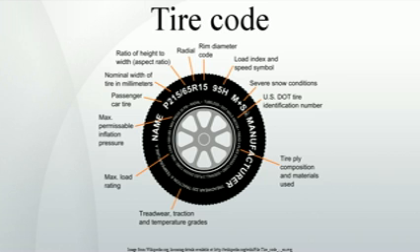MO: original tires for Mercedes-Benz. MOE: Mercedes-Benz Original Extended. N0, N1: original tires for Porsche, where the number is 0 for the first approved in that size, 1 the second. Star: original tires for BMW. RSC in a circle: BMW Run Flat System Component. TPC: General Motors OE fitments. AMX: Aston Martin OE fitments. 100T commonly appears after the tire size, meaning standard load inflation table 100, and speed rating T.